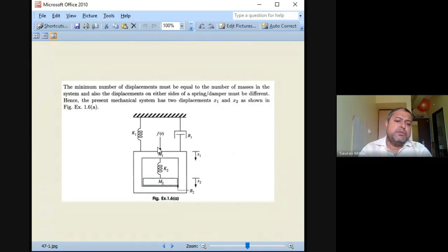So what we'll be doing is finding the transfer functions of the system, that is X1 by Fs and X2 by Fs, and how to find them. Whatever equations we write in terms of dx1(t)/dt or dx2(t)/dt, there will be two time domain equations, one at node X1 and another at node X2. Then we are supposed to find out the RLC FV, that is the force-voltage equivalent, of those equations.